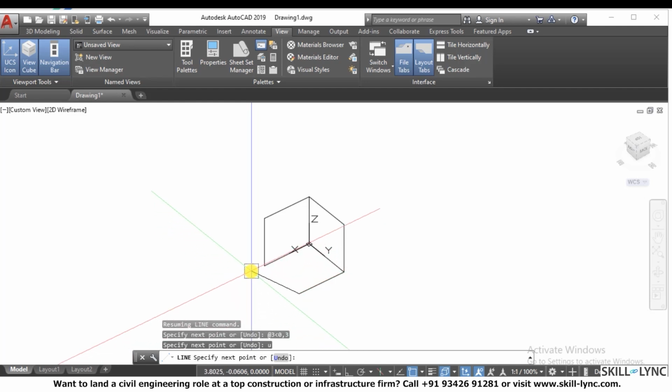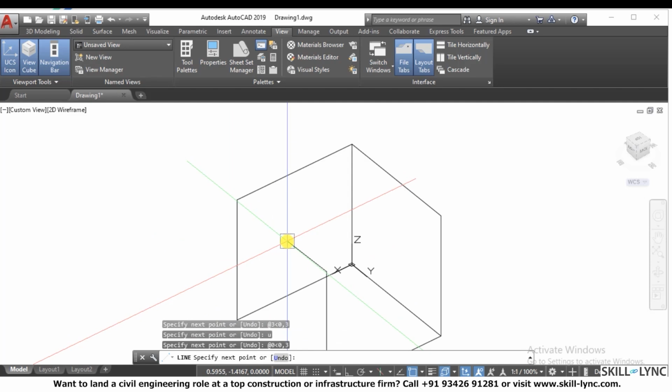So the line is coming over here. But at this moment, we require a line which is perpendicular, straight. So in this case, this is a 0 unit line. What we need to do is create a line with 0 unit of length at an angle of 0 degree, but the perpendicular distance is 3 units. This is exactly what the concept is all about.